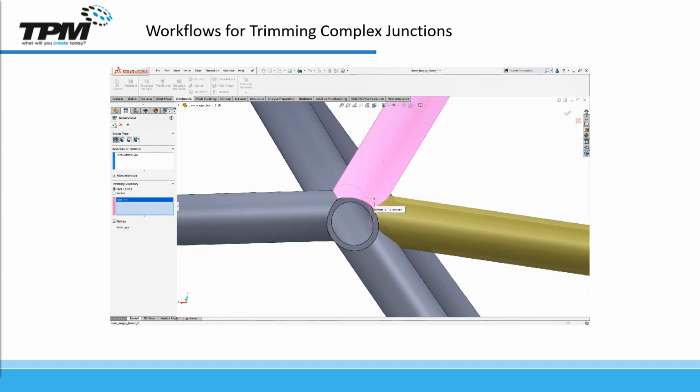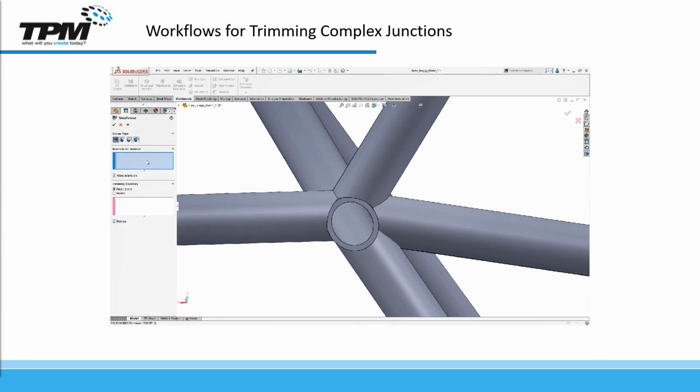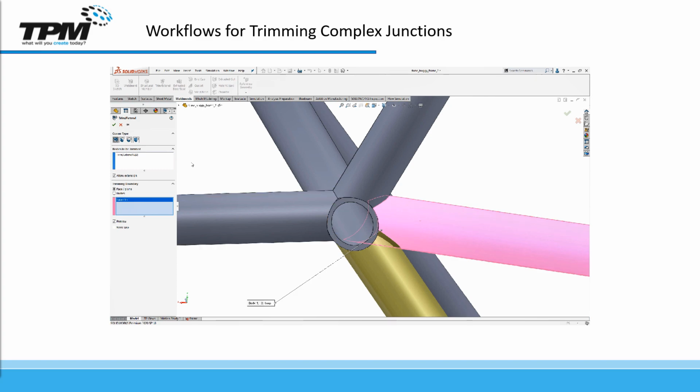And then once we do that, we see we have pieces in between that are intersecting. The objective is to remove those pieces so that the profile can be actually manufactured. One last piece here. So you need to select discard on that instead of keep, and there you have it.